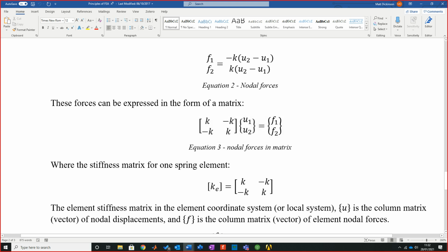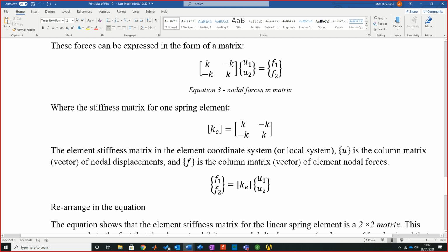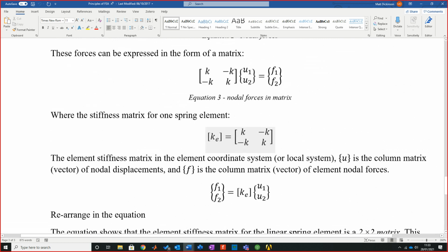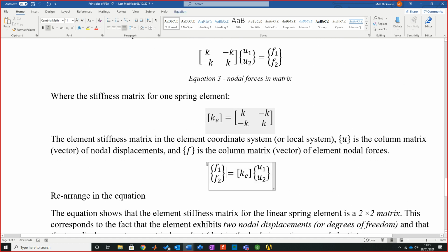If you then look at this as a spring behavior, what you end up with is a so-called stiffness matrix. What it actually does is it describes that node in its ability to move in all of the 2 component sets that are there. So the rearranged equation of this, apologies, sits like this. But this is only on 1 node.